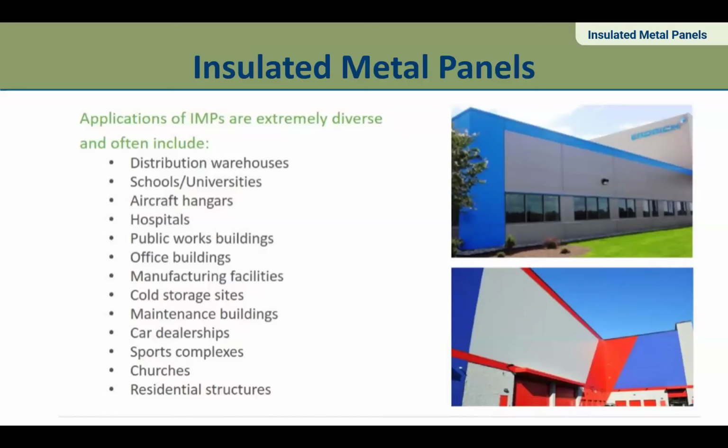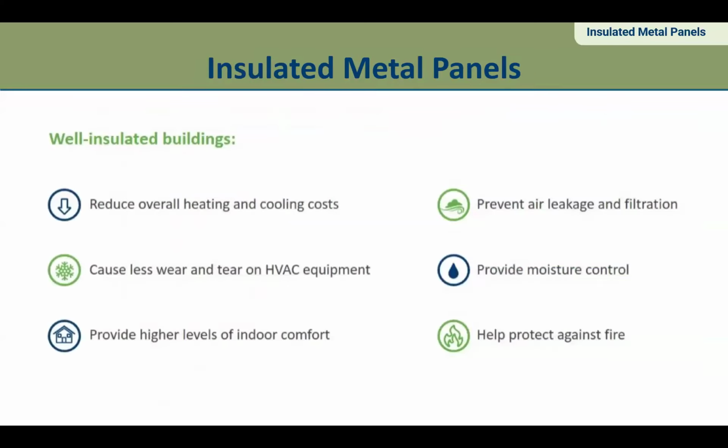The only thing that I'll say in terms of using it in all these different building typologies is that this product system really only works with metal frame or concrete frame buildings. If it's a wood frame building that's not mass timber, you're going to have issues because that timber is going to dry in and compress, but the metal panel is not going to experience that. So you're going to have issues trying to integrate this into a wood frame building.